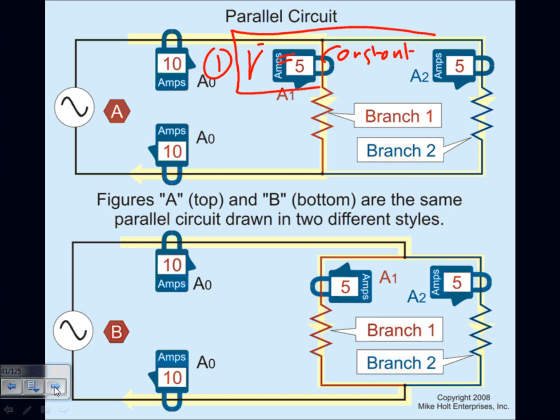Maybe this is the single most important thing about why we adopted the parallel circuit for power transmission around the world, because the voltage stays constant. Every time I turn the light on and off, what's going to happen to the voltage across these plotters and printers? It stays almost constant. It fluctuates within 5%, up and down, but it stays constant. It's not going to double or triple or cut by half or by a fourth.